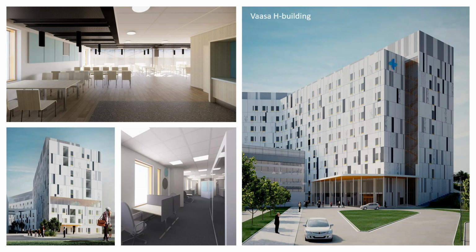And I guess what I mentioned during the presentation and during the demo is that you could move data which already existed. So I'm assuming those 5 projects, especially maybe that FASA H building, were already started before BIM 360 design and then moved on to it, or maybe one of the latter ones. Yeah, actually all of them were old projects or already started. That's what I mentioned in the presentation as well. It's quite easy to take that central file, detach it, and just say, okay, we're going to push this into the cloud now. Everyone gets a local file, and they're good to go.